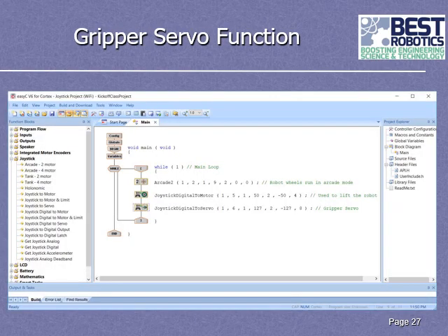So now you have completed all the software you need to run a simple robot. This code will allow you to move the robot around in arcade mode, it will allow you to raise and lower an arm, and it will allow you to open and close a servo. Now, if you decide in your gripper you want to have 2 servos, or if you want to add another motor, you would effectively add either a second servo or a second motor, and you would do it exactly the same way as we did the previous ones. Again, you'd have to pick a port that's open and pick some buttons that haven't been used yet, but it's the exact same process to add more of those in here.